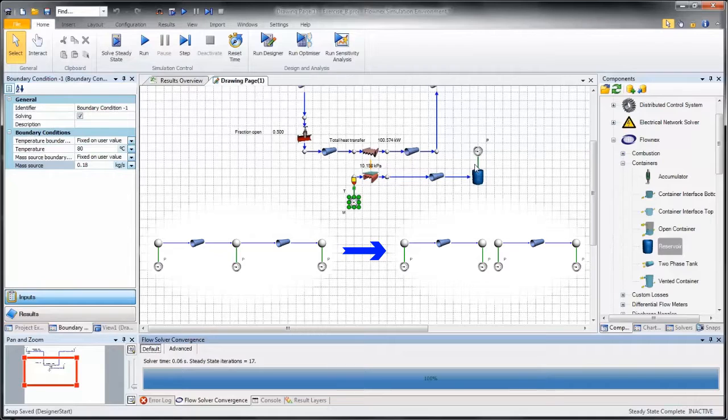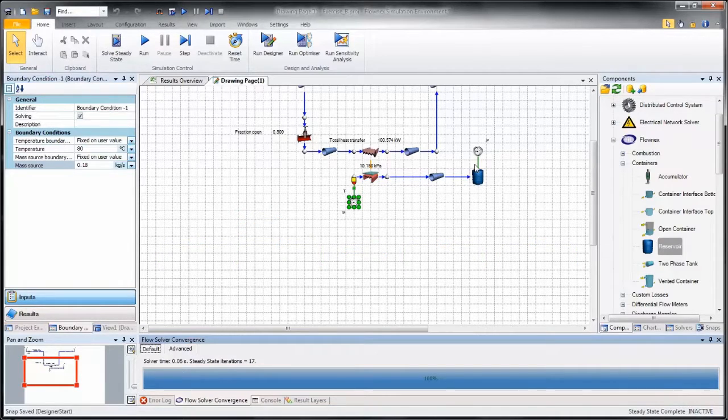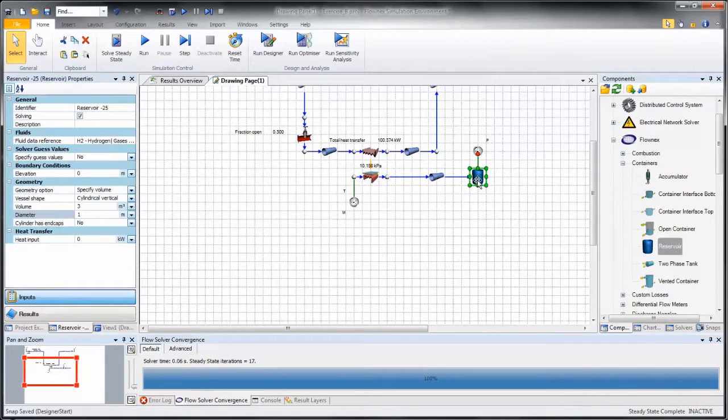And if my mass flows on both sides are not exactly the same, a mass source will be created on that position, which will lead to a further change in temperature. For our case, we know that the system pressure needs to be controlled from our reservoir, so we need the pressure specification on this point, and will therefore employ it with the appropriate level of caution and due diligence.